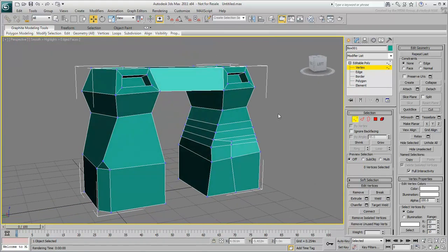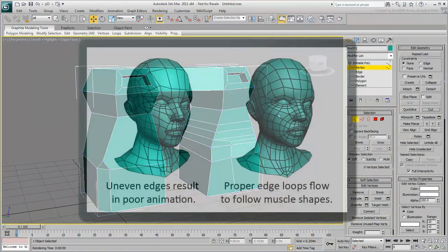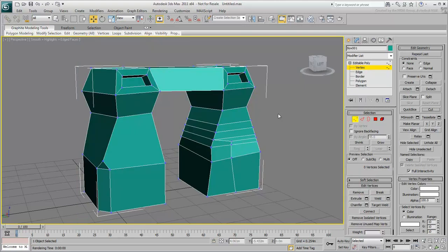As you model and subdivide, you want to control the smoothness of the surface. Here are some guidelines to keep in mind. When you subdivide polygons, it's important to create polygons with 4 sides, called quads, whenever possible. Create smoothly flowing edge loops in an even grid pattern. These guidelines are especially important when creating curved surfaces in areas that bend during animation. Otherwise, you can end up with unpredictable smoothing and smoothing artifacts such as bumps and holes. Creating an even mesh is also important for unwrapping, rigging, animating, and so on. Part 2 describes how to build a jerrycan using the techniques shown in this movie.